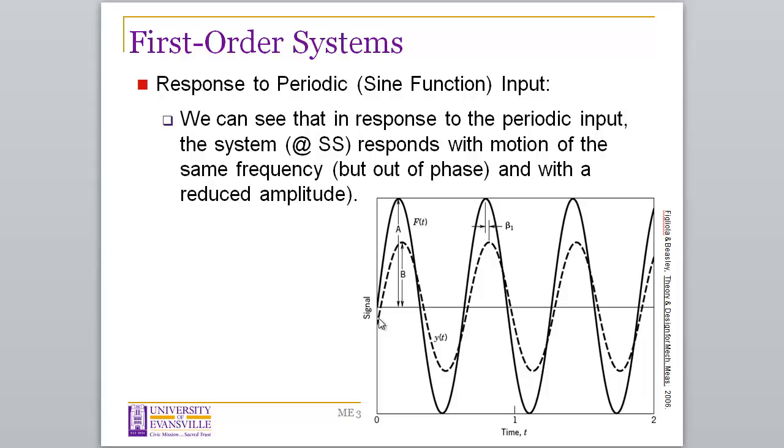The dotted line, on the other hand, represents what the measurement system is outputting. And you see that it is of reduced magnitude, the same frequency, same number of oscillations per second, but it has a reduced amplitude and it has an offset as well. And those are the two things, primarily the amplitude change, that we need to understand.